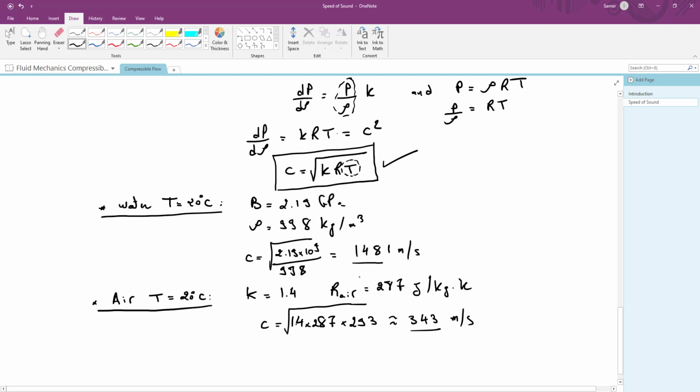In general, the speed of sound in gases is much smaller than the speed of sound in liquids. If you look at it this way, in liquids the molecules are much closer to each other, so they help transport the vibrational energy at a faster rate when compared to gases. The particles in gases are much more widely spread, and as a result, this slows the transport of the vibrational energy, which is the pressure wave.